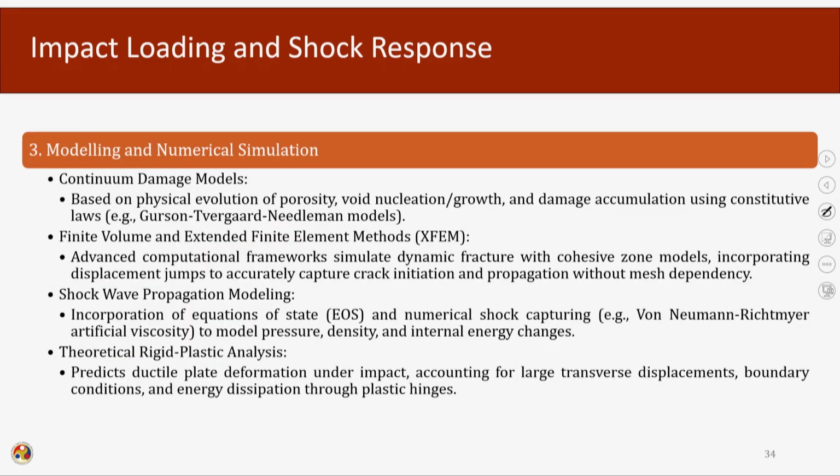Okay. And now, using the data from the experiments, the constitutive models can be made. And these models, combined with information about the damage propagation, the microstructural formation, the grain size, porosity, and using all these factors, the continuum damage models, or the damage models for the continuous surface, can be developed. These developed models are based on the physical evolution of porosity, void nucleation and growth, and the damage accumulation using constitutive laws.